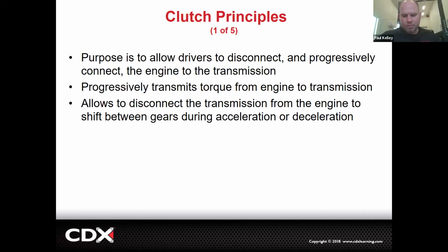It's the main reason I haven't delivered this thing yet. I did a whole bunch of service on it. One of the things was I changed the hydraulic fluid, so brake fluid and clutch fluid. And bleeding a clutch can be a little bit tricky. So I just tried to loosen the bleeder and let it gravity bleed out, and kind of bottle feed it, the rabbit feeder type of thing. But one way or another, now it's got kind of a spongy pedal.